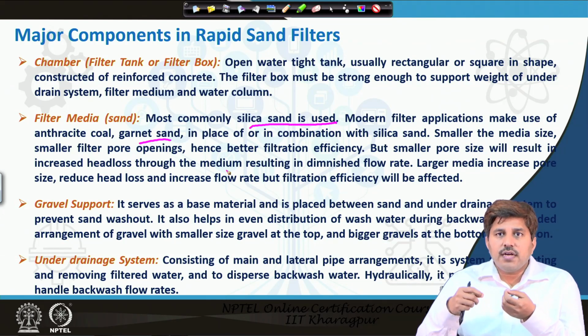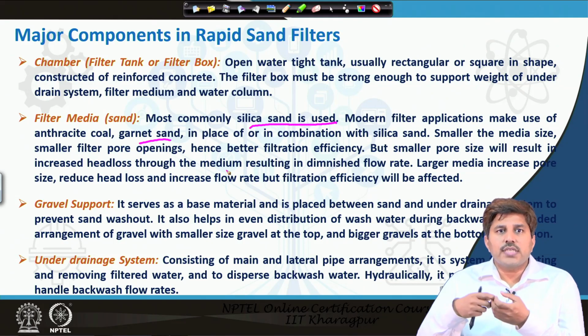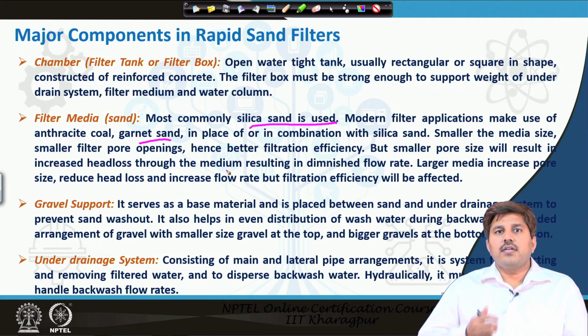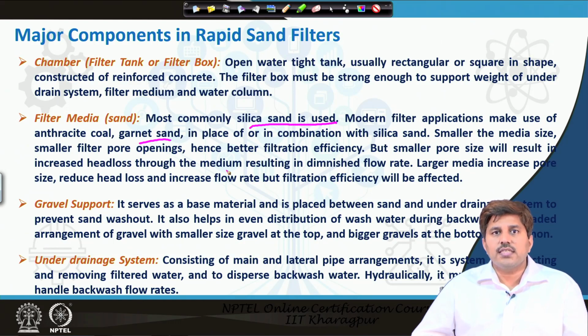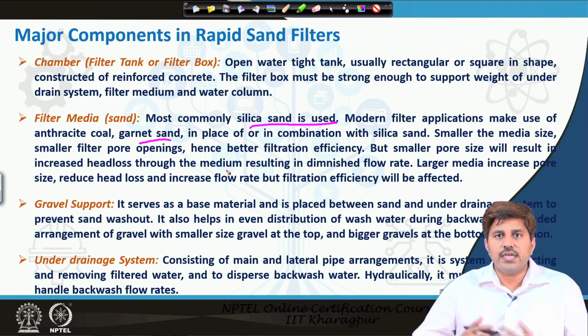The larger media will increase the pore sizes, okay. So, head loss will be reduced, and flow rate will increase, however the problem is that the filtration efficiency may get affected. So, we need to choose an optimum combination.